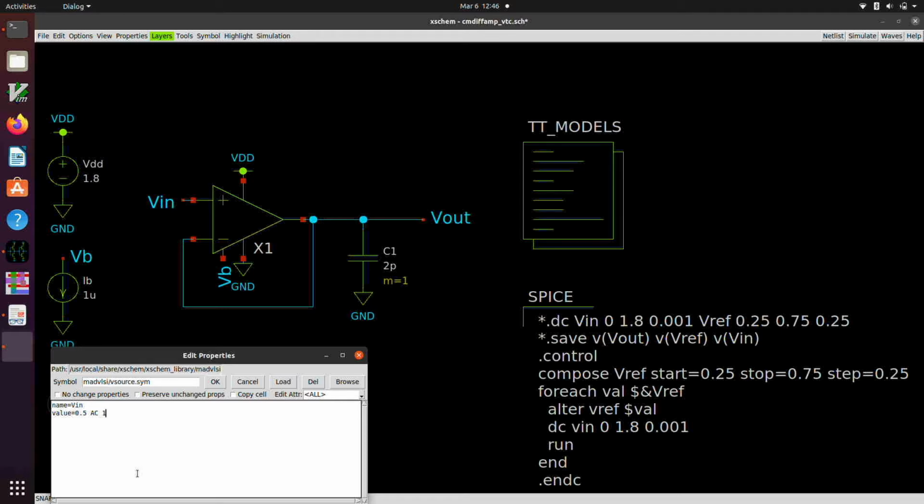So even though the gain of this amplifier may be, oh, I don't know what it was, 150, 60, something like that, and we put in 1 volt, we would get out more than the power supply. We are still able to do this with a 1 volt signal. And that's convenient because when we plot the output voltage with an input signal of a magnitude of 1 volt, we will have directly the gain of the system, and we won't have to subtract out or divide out the output or the input signal. So that's the first pro tip for doing these sorts of AC analyses.